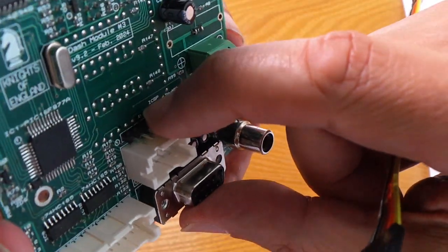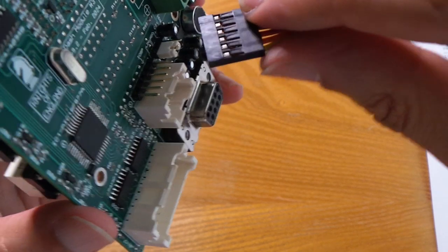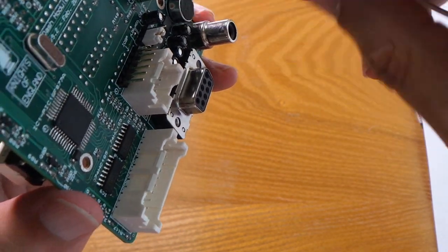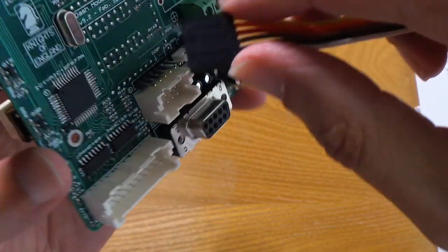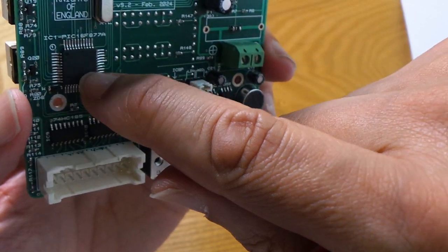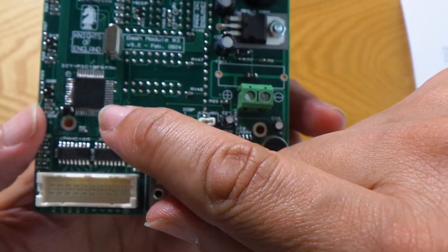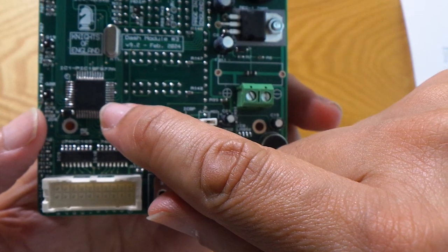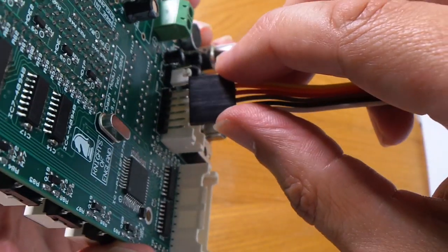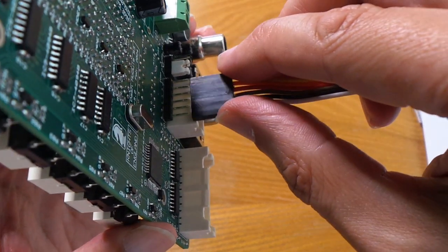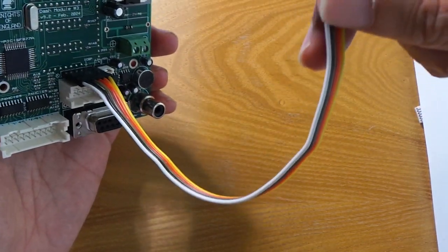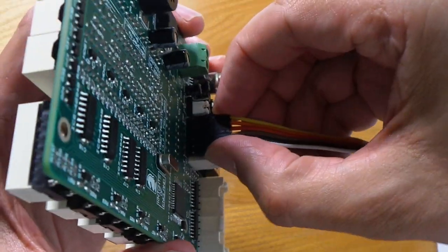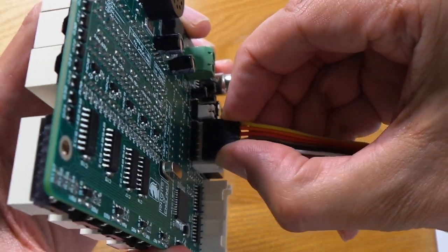This 6-way connector here is for programming the unit, and if you want to reprogram the unit, we can recommend that you get something called a PICkit manufactured by Microchip, who are the manufacturers of the microcontroller, which is this one right here, and that's a Microchip part number PIC16F877A. To reprogram it you'll just need to put an in-circuit programming connector on there and put the other end into the PICkit device, and I'll put a link to PICkit devices in the description below. So let's just remove that.